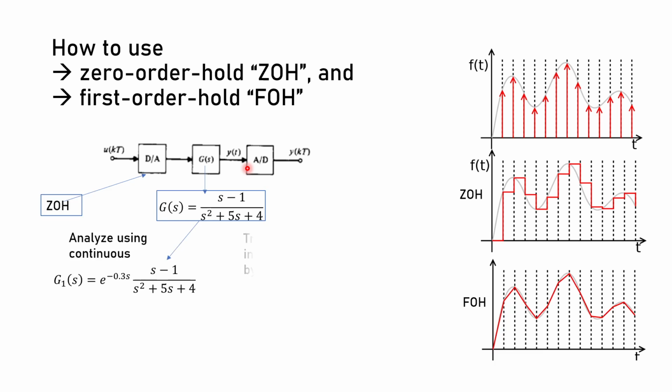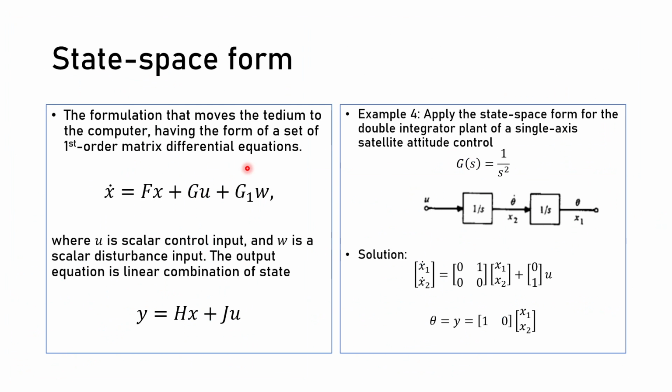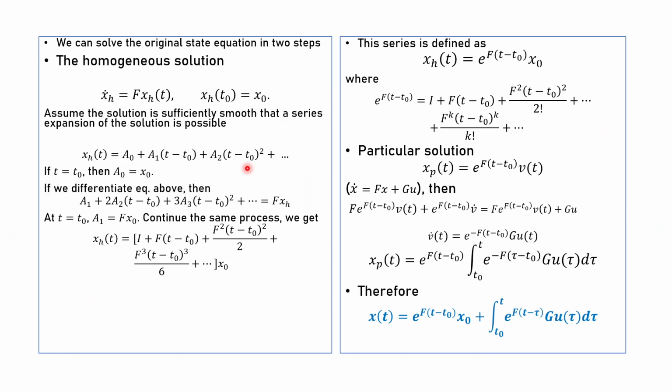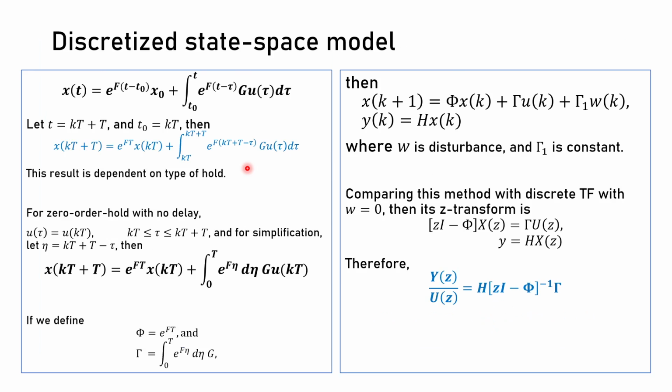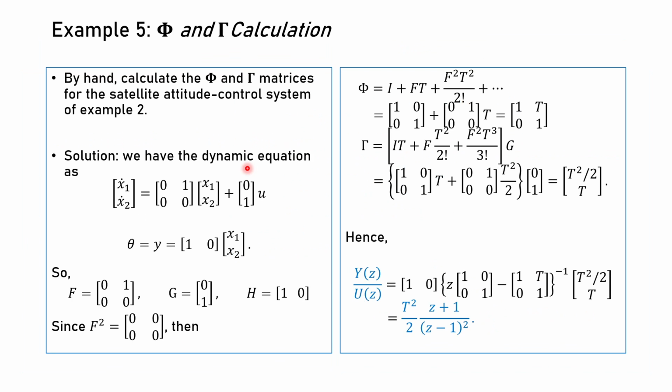So in some sense, the state space form gives you more information on the state, but for single input, single output analysis, you only have the relationship between output and input, but not the internal state. In our case, we have two internal states, right? So the state space form gives much more information and more ways to do the analysis, and also more ways to design a controller. You will see in the future.